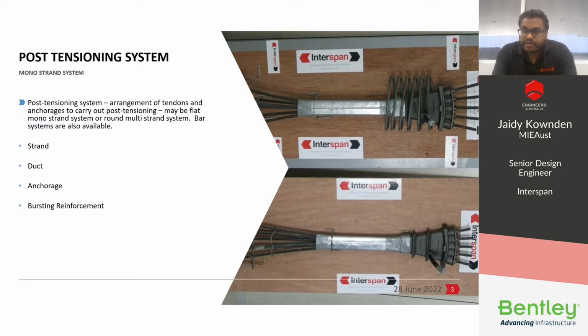On the screen at the moment, you can see the multiple components we have in the monostrand system. The strand is a cable that we will apply the load to. The duct is a grey flat conduit that will encase the strands. On one side of the anchorage, you will have an onion, which will hold the cable into the concrete when the load is applied, and the anchor where the stressing block is applied to apply the stress.